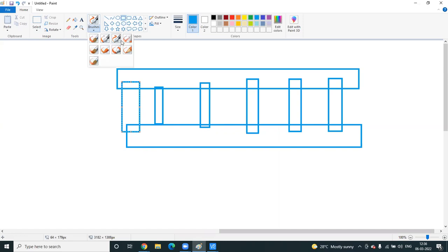So let us assume this contact resistance or via resistance is 6 ohm. Total 6 resistors are there. If all 6 are 6 ohm in parallel, what is the equivalent resistance? It will be 1 ohm. The resistance reduced means we can pass more current. Okay, more via or more contact we can have.